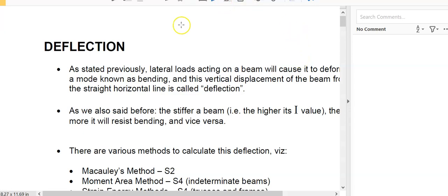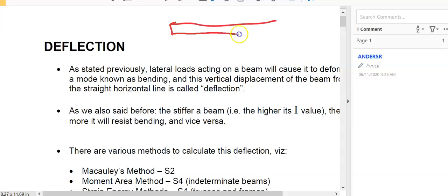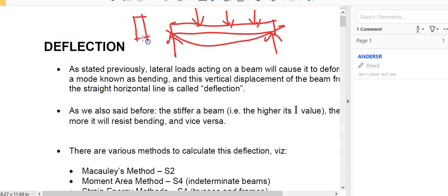Right, so if we have a beam there, and there are the supports, and of course by nature of the member, it's a horizontal member, so loads are acting over there. Of course the beam will want to bend like this, and these loads, because they act across, if I drew a section of the beam, these loads act across that section. We call that lateral loads.